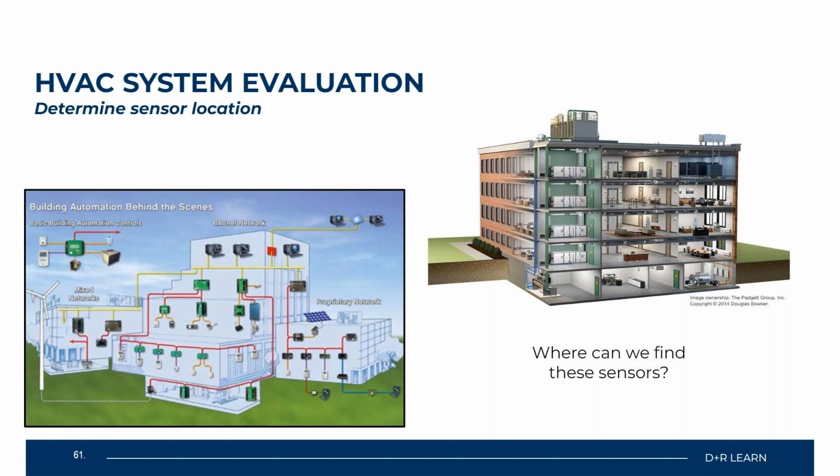So once again, sensor location is extremely important. On the electrical side, that's just going to be cut and dry. You're going to pretty much put those sensors in line with the electrical application. But when it comes to sensors that actually test for something such as wind, air, or water flow movement, those will need to be placed in line with that mechanical function or action.